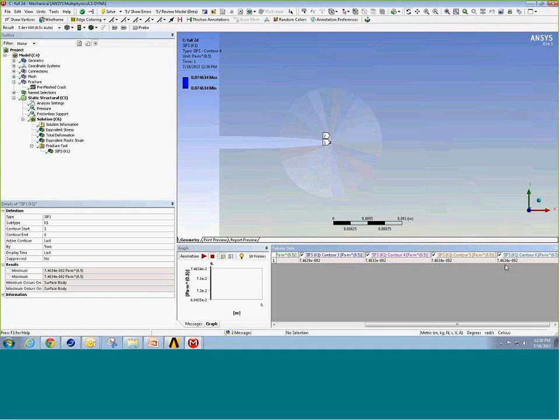By the sixth one, for this particular case, we have a value of 0.0746, which also shows up in the details. Now you can compare this value to the material fracture toughness to determine if this crack would propagate.